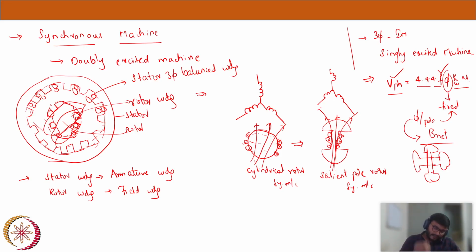Now in the case of a synchronous machine, if you see my excitation, whatever I'm giving, it's completely DC, right? My secondary excitation which I'm giving to the rotor winding is a DC. It's completely DC, free from any alternating supply. Now it won't be drawing any lagging or leading loads. It will not draw any lagging magnetizing current, and I just have to keep a DC supply or a battery bank. Some kind of way we have to find to give a DC supply to my rotor. That's it. There is no need to take care of the magnetizing current in the machine.